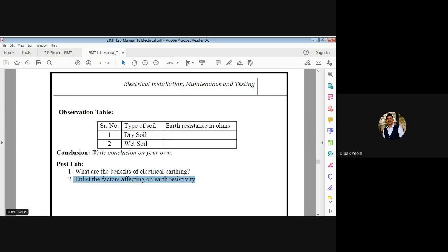That is called the footing resistance, a word I already told you. If you search for this word on Google, you will get information about footing resistance, the resistance available at the foot of a particular tower. We have to maintain this footing resistance at less than 5 ohm. That can be the tower of our transmission line, the electricity pole near our house, or the tower for the locomotive overhead conductor.